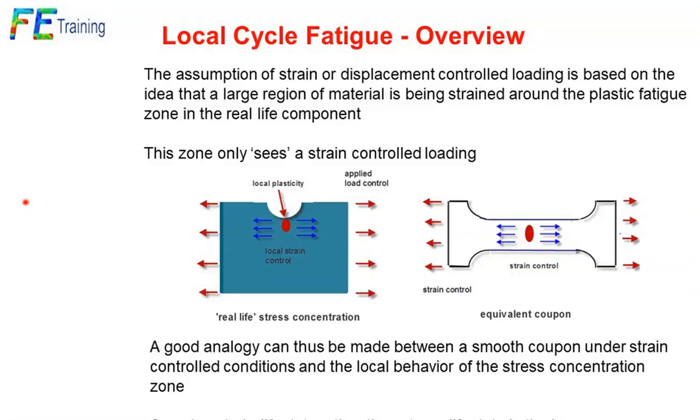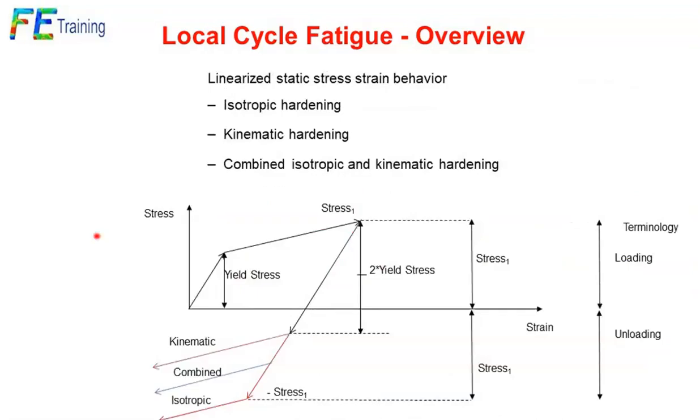It's not a number, it's the presence of plasticity. Now, a very quick review of plasticity. We've got our local elastic response limit here. We reach a yield stress. We have a bilinear approach. We could say we use a tangent modulus, and we just simplify that. We reach the limit of our loading. We unload, and we get down to some locked-in residual plasticity.